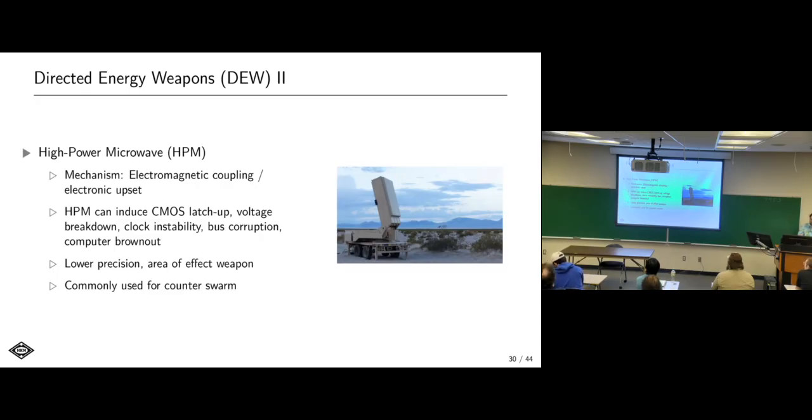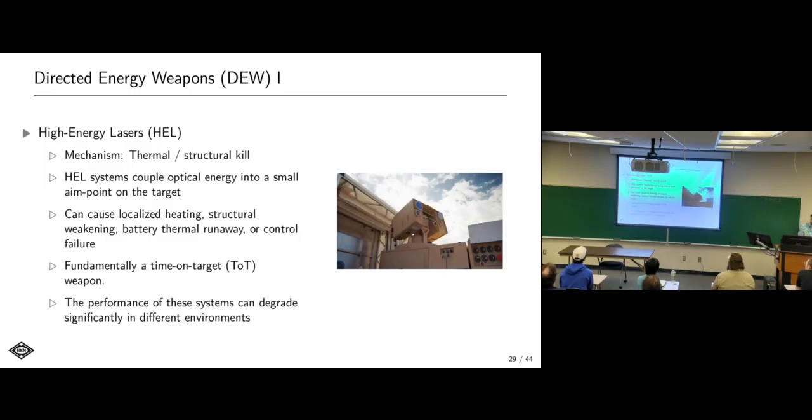The issue with the laser stuff from a pulse versus CW perspective is most assets won't even fall from a single pulse. So you either need to keep pulsing or hit it with CW. A lot of the older systems are pulsed because that was all they could do. But we've drastically improved optics and electronics to the point where we can afford CW now from a power and heat budget. So they're becoming more CW. Time on target is such a big deal, especially when you look at some of the kinetic interceptors. I talk about the IR sensor there.